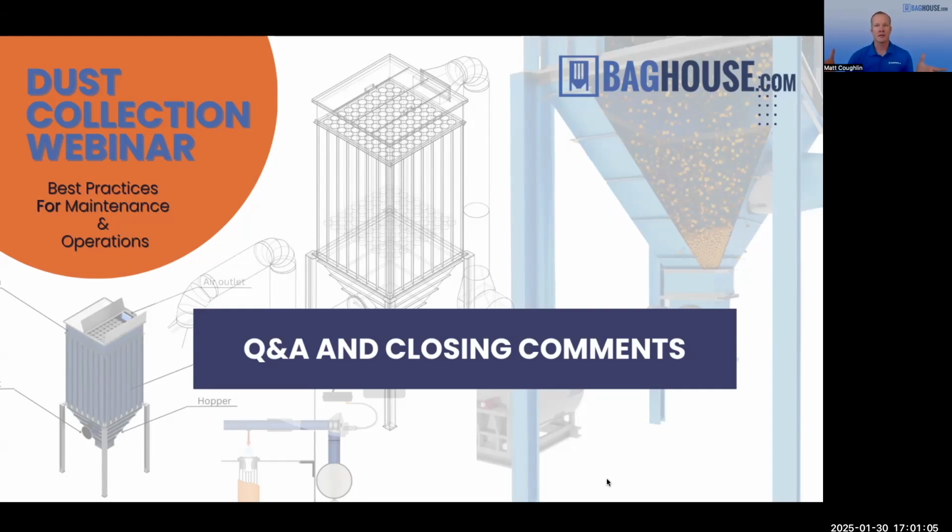If you have a rotary airlock, for example, the idea is that you have a leak-free, airtight piece of equipment that provides an airtight divider between the hopper, which is at a certain pressure, and the atmosphere below the hopper, which is at regular standard atmospheric pressure. What can sometimes happen is your rotary airlock, which is a little rotor, has tips on it, sometimes made from different materials, but they're designed to have a really tight clearance to maintain that leak-free, airtight operation. So the dust falls through, but the air basically stays at its pressure. When those tips wear out, air rushes through there. It becomes a leak source. Now you have air coming through your rotary airlock in the wrong direction, and it can cause things to bridge and make it difficult for that dust to discharge out the bottom.